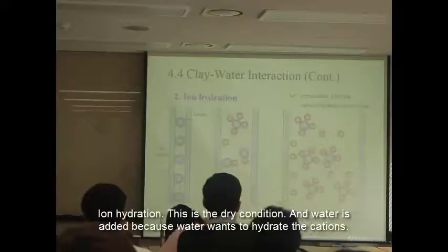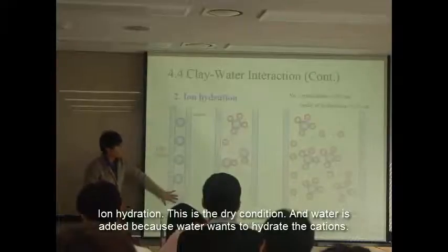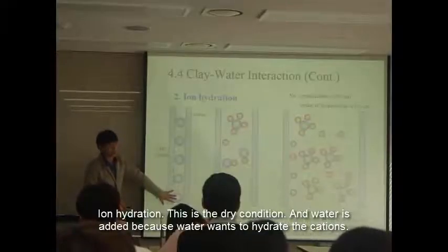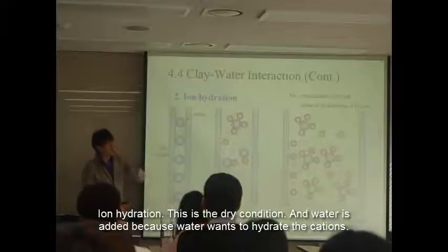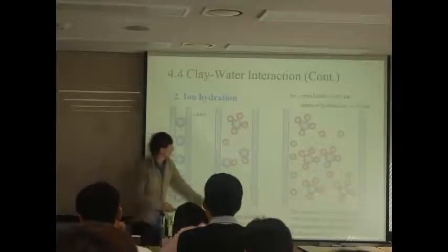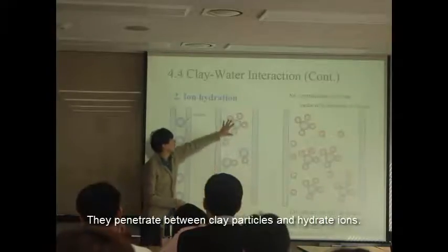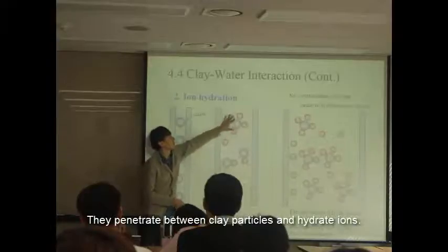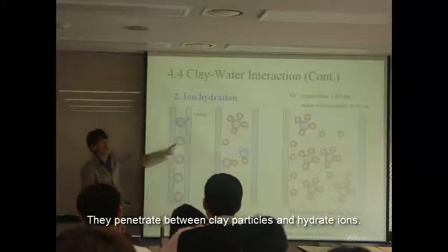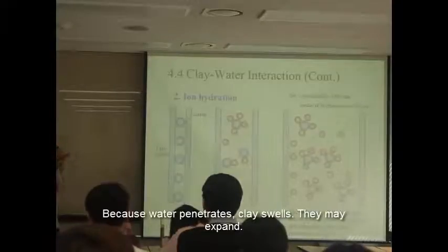Another is the ion hydration. Dry clay, this is dry condition, and when water is added, because the water wants to hydrate the cation, the cations penetrate into the clay between the clay particles, and the hydrated water. Hydrated cation or ion. So then, because the water penetrates, what will happen? Clay swells. The volume will expand.